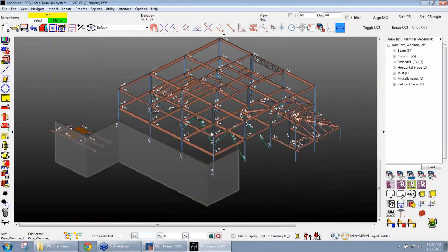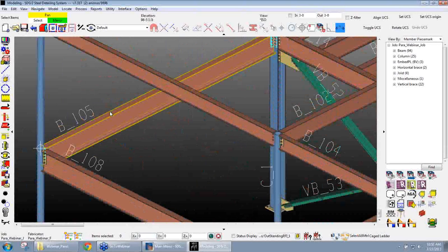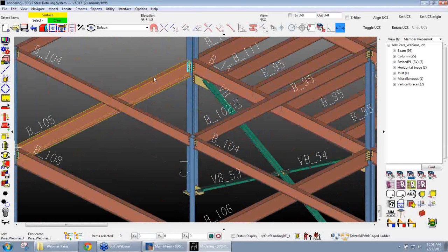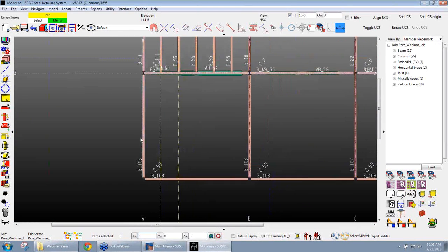All right. Another parametric that's commonly used that I see quite a bit is going to be the beam outrigger shape. Just come up. We'll use this particular beam here. I'm just going to surface on top. Potentially, before we get to add in this outrigger, maybe I want to have X amount, maybe 7 of them, 7 different spaces in here. And I want to have them be evenly spaced. What's an easy way I can go through and find that information so I can add in these outriggers?